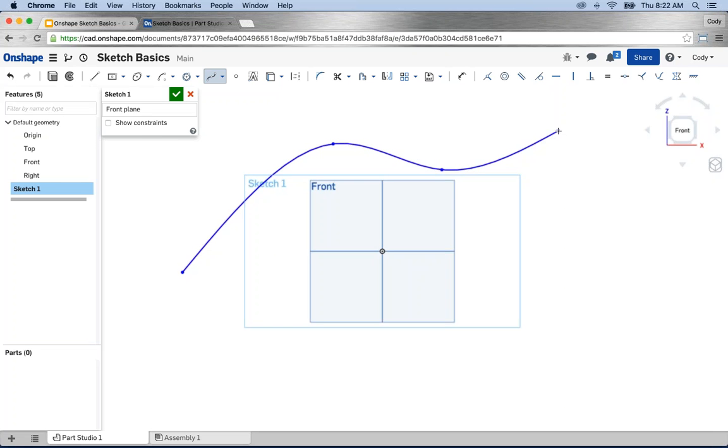If I start getting into tons of detail, there's lots of points where I have to adjust to get it just the right way. So in general, especially if you're concerned about curvature or smoothness or any of those kinds of things, the fewer points, the fewer times you left click in the spline, the smoother the shape will be. Some other tips, you'll need to escape out of it once you're done.